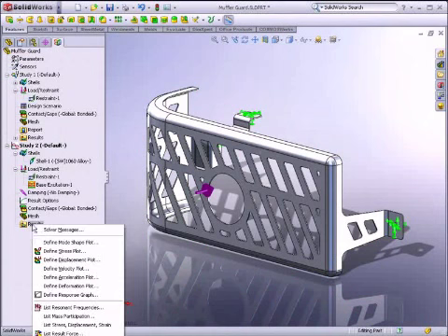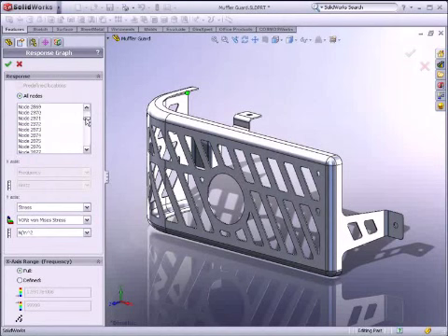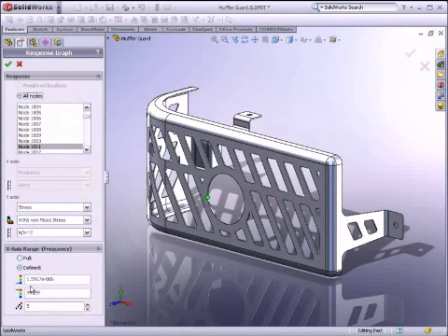To get an idea of where the part deforms the worst, we will define a response graph. First, we must find the node that best describes the application by looking at the graphics window. And then change the x-axis range down to normal operational levels. This graph shows us where the part is most likely to fail.